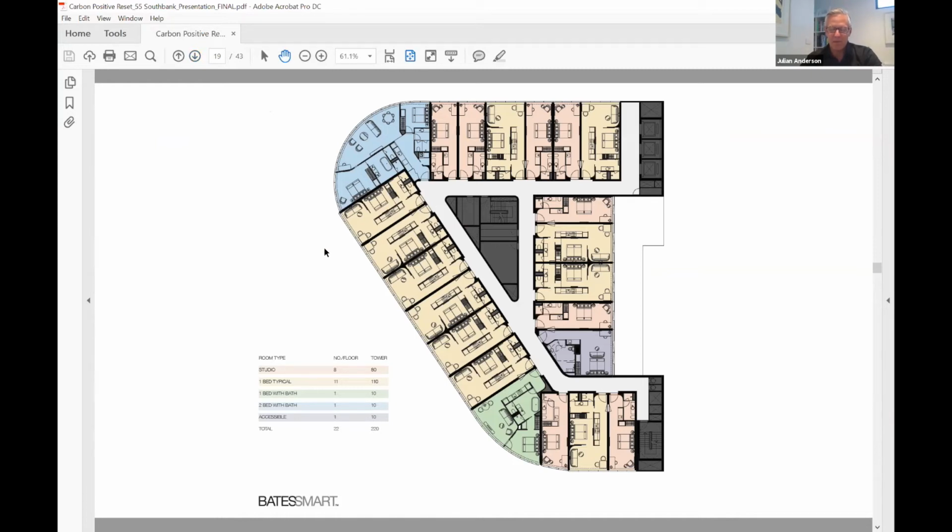They do narrow towards the top of the building. So the CLT panels are 150 millimetres wide at levels 9 to 11, 135 mils at levels 12 to 14, and 105 mils at levels 15 to 17. So this has minimised the weight of the cross-laminated timber required for the structure. And there are only 5 room types in total.